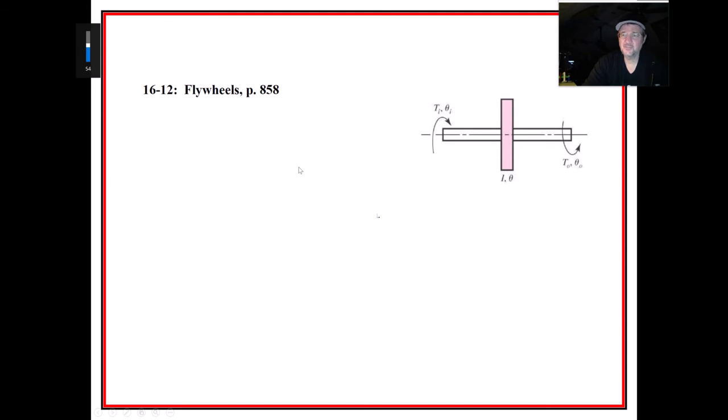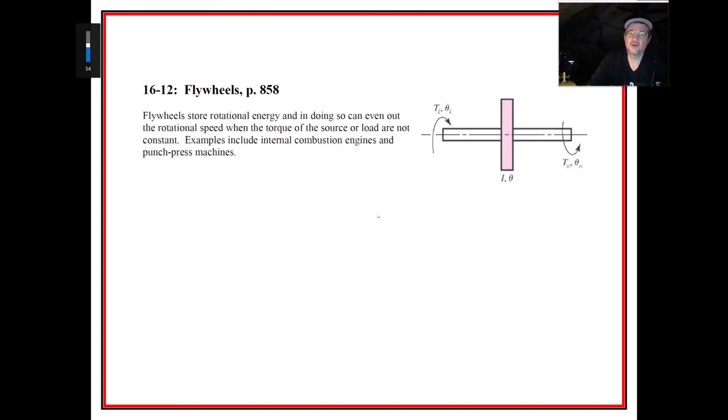And the last topic I think I have in here is flywheels, and the purpose behind them is to store energy and to smooth out a ride, right? You remember in our single-cylinder engine that there's a power stroke every other rotation, and that power stroke's only 1/2 of that rotation. So there are 3 more half rotations needed to go around, and that one half rotation is the only time where there is some real impetus for it to go around.